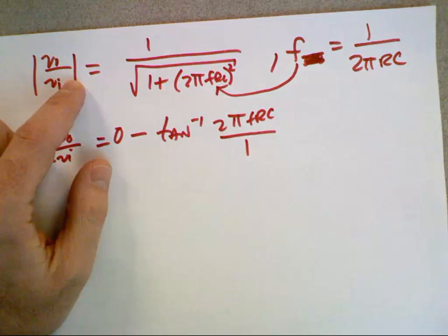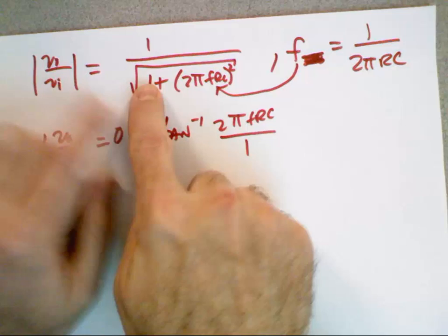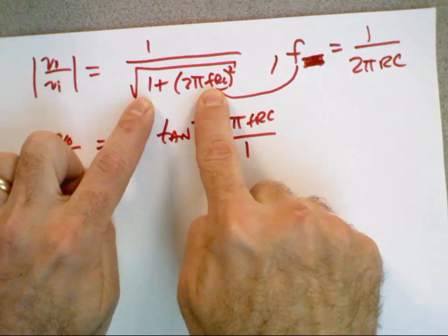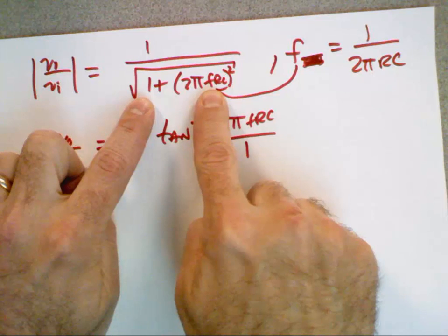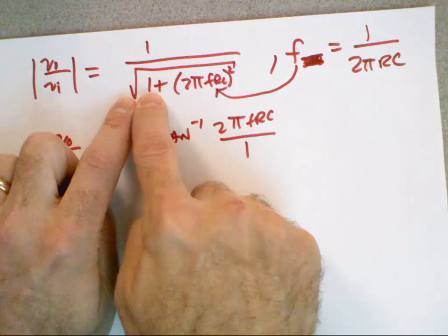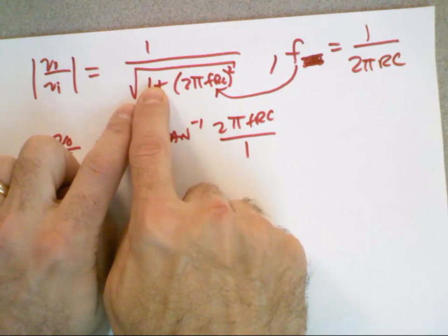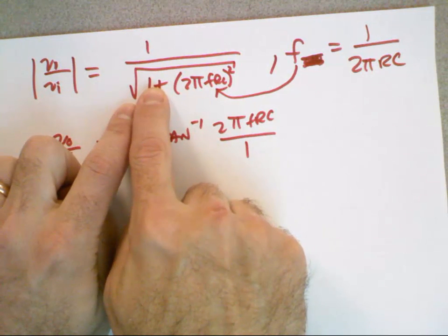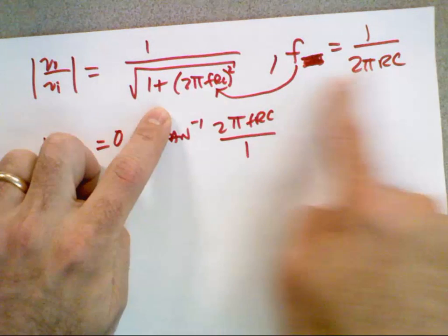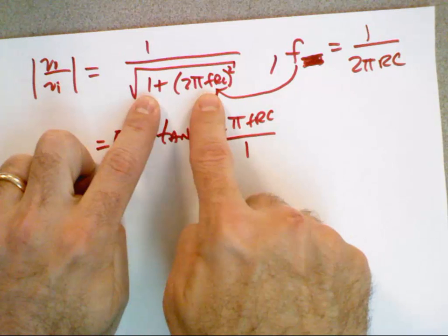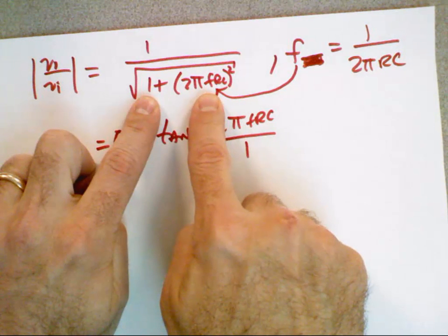The thing about the 3 dB frequency is when the real part and the imaginary part become equal, that's when the imaginary part's starting to grow bigger than the real part. That gives you 1 over root 2, which is 0.707, which is minus 3 dB down. So it's an arbitrary number you just plug in here. It's when the real part and the imaginary part are equal. Does that make sense?